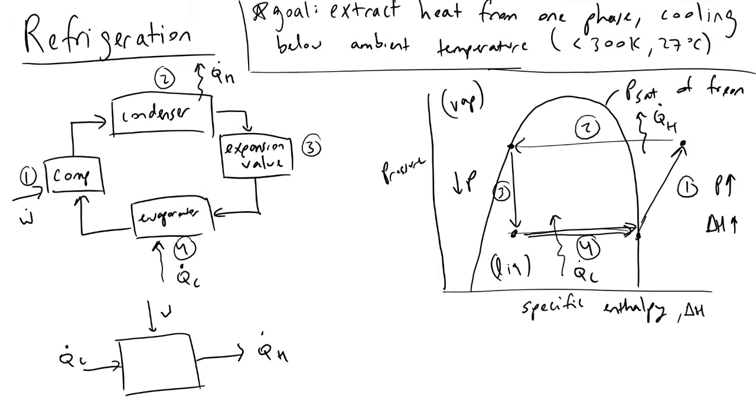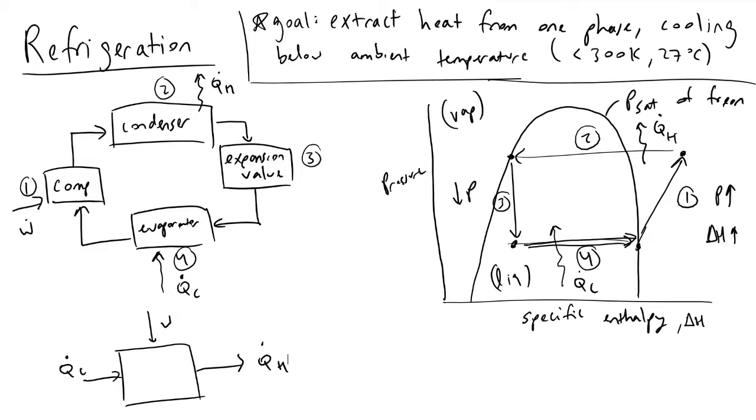And another important thing when you're generating these plots, so I'll call this table 1, is that the control volume is the Freon. It is the stuff inside of the refrigeration loop itself. We're not looking at the car cabin over time. We're not looking at the exterior. We are only looking at how the Freon is evolving as a function of specific enthalpies. So that is an important note to make if you are going to generate these plots or try to understand this stuff better.